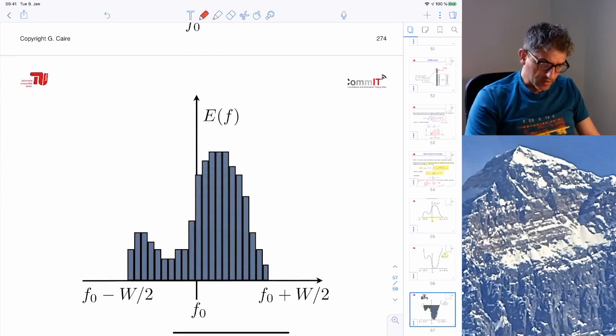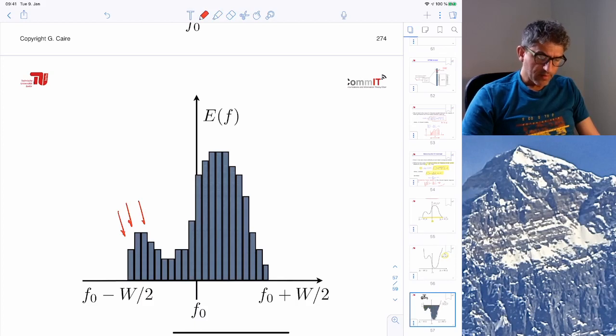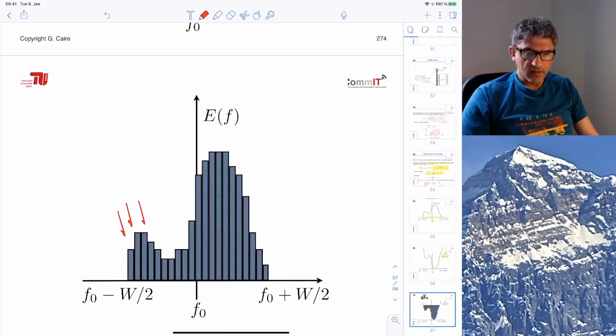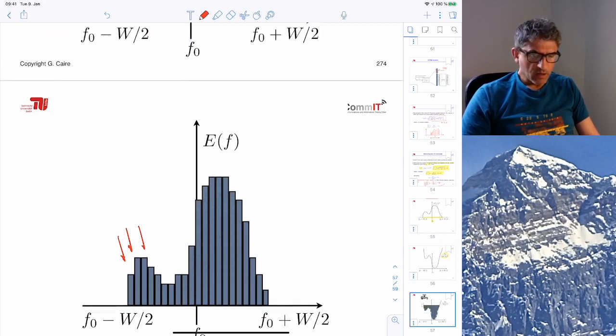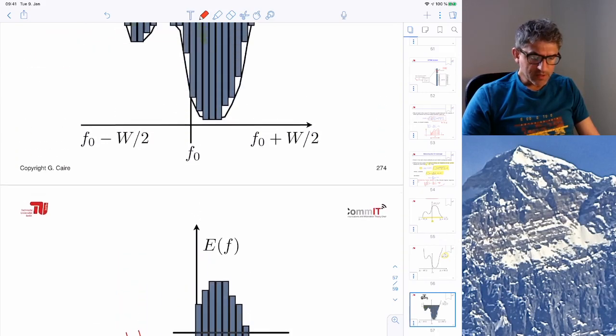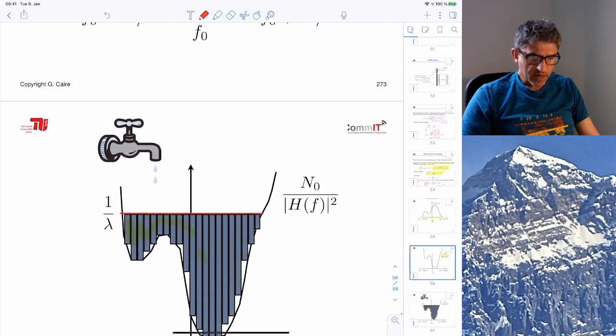Each one of these little slices is a subchannel in the frequency domain, and we treat these as parallel channels in the frequency domain through the OFDM algorithm. If you take K, the number of subchannels, very large with respect to the length of the impulse response, this is arbitrarily close to capacity achieving for this frequency selective channel.